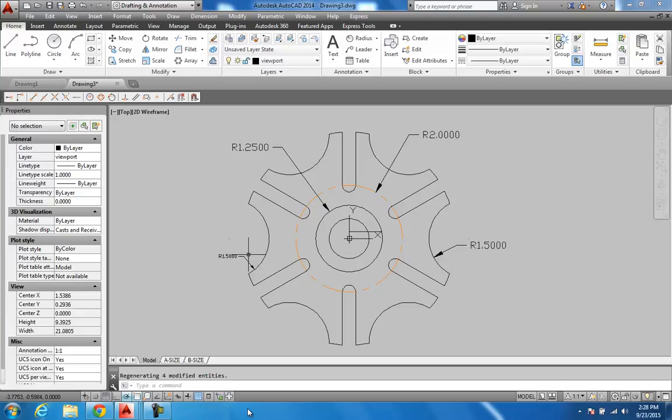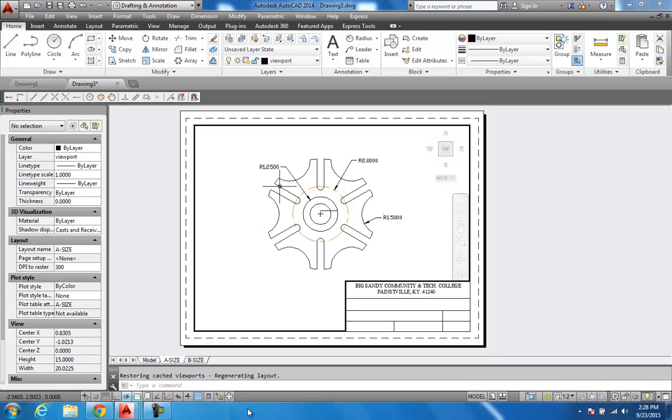So it's very important that you figure out what scale you're going to put the part on the paper with, and then go back and fix your dimensions to make sure all of them get transferred onto the paper successfully. But again, if you guys are having any trouble with any of this, just please let me know. But other than that, this looks really, really good, and you'd be ready to print.